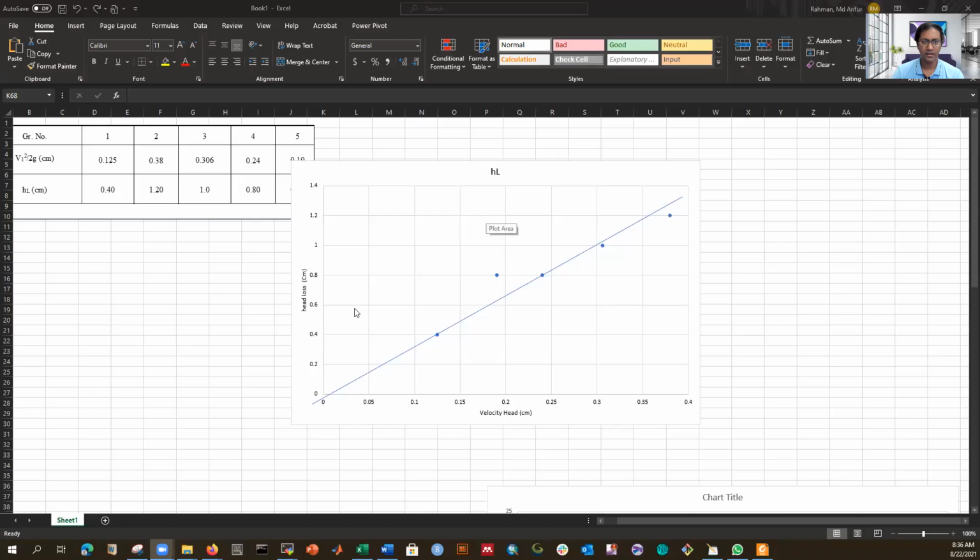You can calculate this way. So these are the Bernoulli's principle we are verifying. We're verifying if the total energy at every section is constant or not, and how much head loss we have in between 2 sections, and how it varies with the length or with the velocity head. If you increase the velocity, what will be the head loss? That's why we're checking for different flow conditions, because for different flow conditions, we have different inlet velocity head. So let me just quickly share my screen right now and show you the graphs.